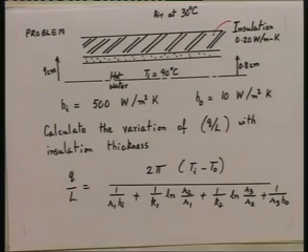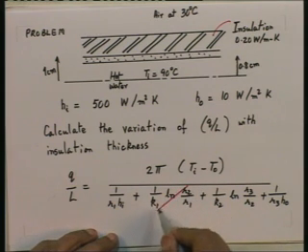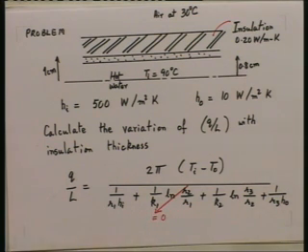Whatever the value, the thermal resistance of this metal tube is going to be insignificant compared to the thermal resistance of the insulation. So straight away let us drop this out; we are not even going to calculate it, we are just going to take it equal to 0. I am going to make that approximation, which is a very accurate one. So let us neglect the thermal resistance of the metal tube compared to the thermal resistance of the insulation, which is coming on the outside. It is quite justified. So with this approximation, what do we get now for the Q by L?